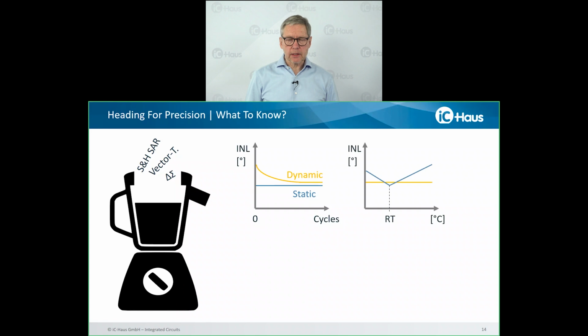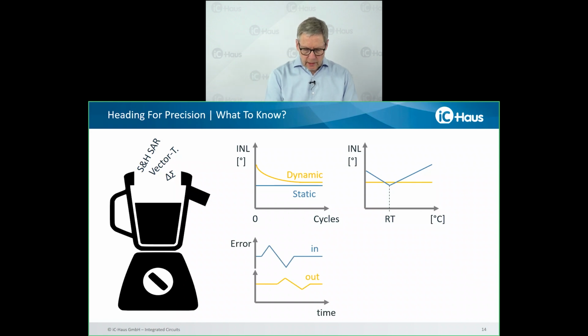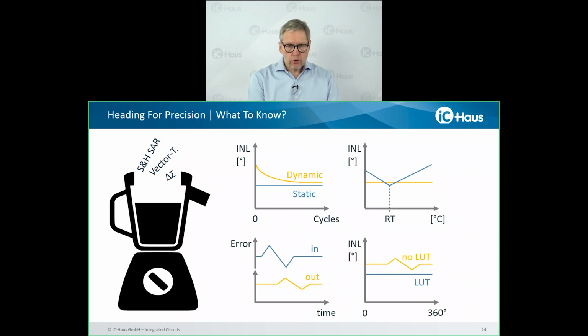This is true at least when you restart at the same temperature as at the time of calibration. If you are dealing with local scale errors, you need to understand that a dynamic correction reacts afterwards, and therefore can only compensate for previous disturbances proportionally. To correct a local disturbance, a lookup table would be nice and required, which corrects the position data to the point.